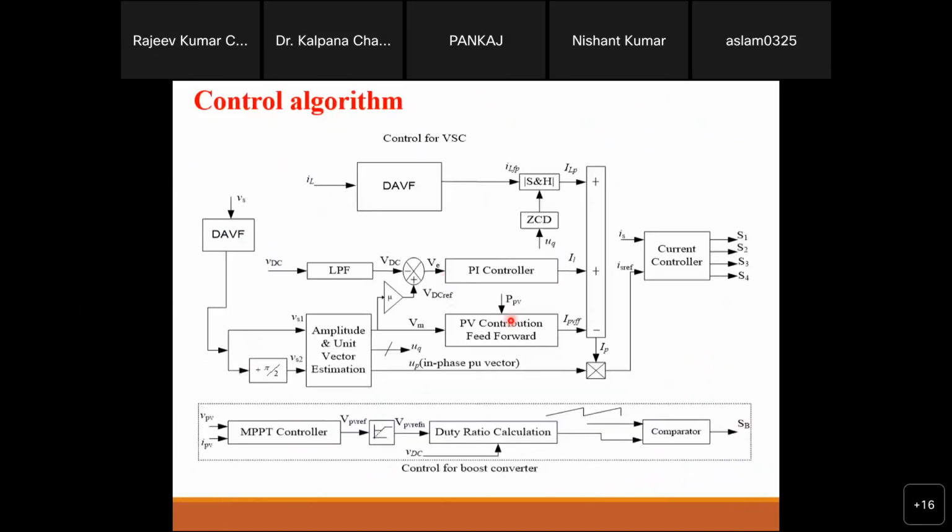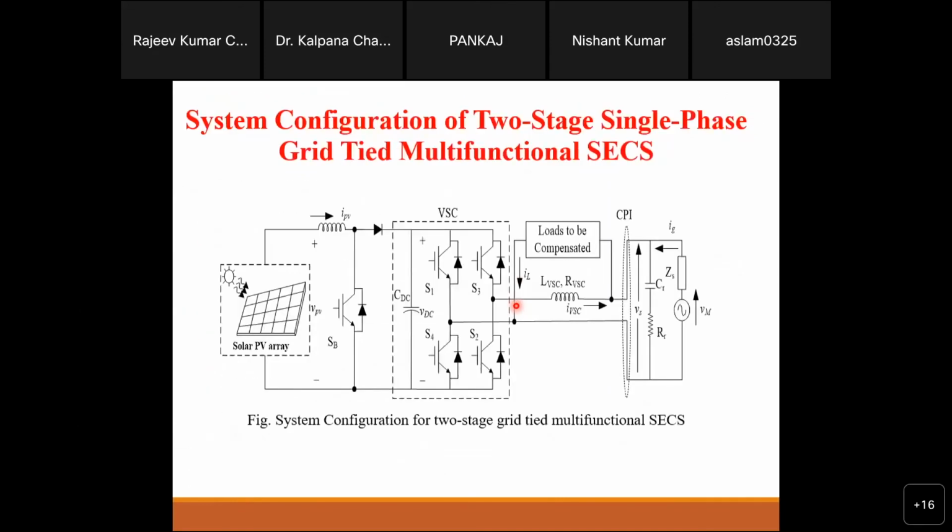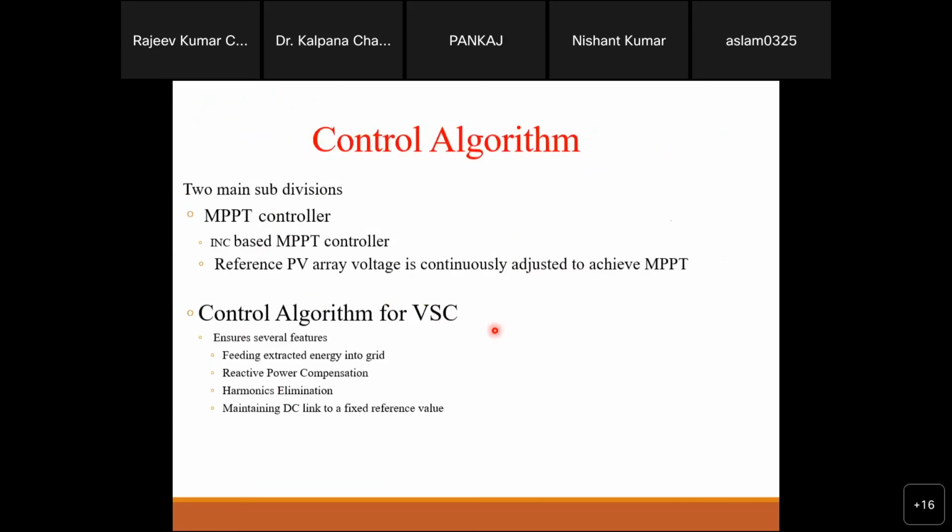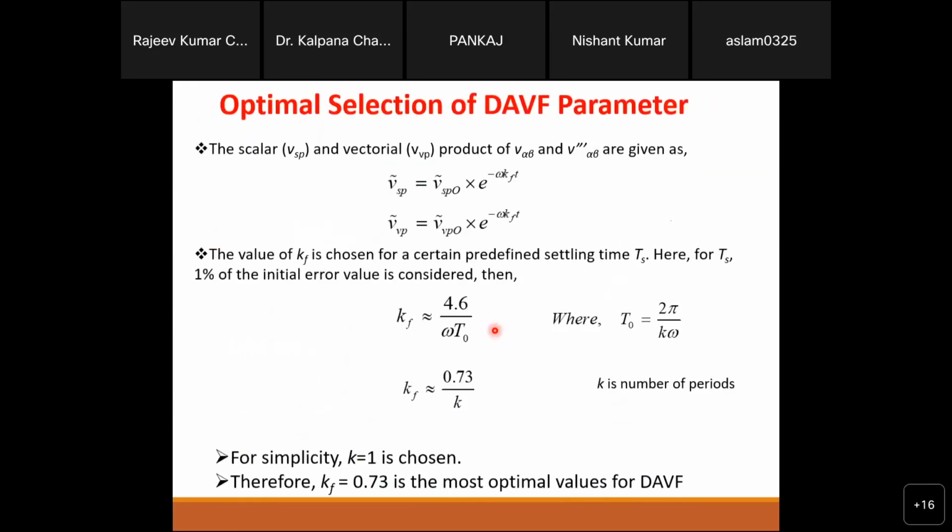For example, here we have PV power; in the place of PV power, you will write wind power. And then on the connection side, in place of this DC boost converter and the panel, you will remove them and attach only the output terminal of the wind converter. I'm not talking about the machine directly, for example a PMSM, type 4 wind generator. So the second converter's output terminal DC component you will attach here. That's it. The rest of the controllers will be the same and it will work like that. So you can use it for that purpose also.